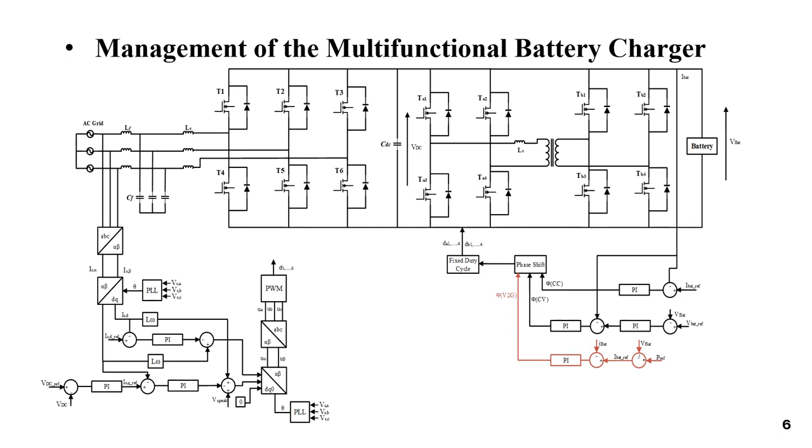During the first charging stage, the current reference is adjusted to an acceptable charging power level. The voltage of the battery increases as it is charged at a constant current until it gets to the highest voltage permitted by the manufacturer of the battery.